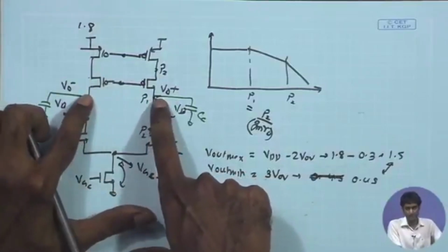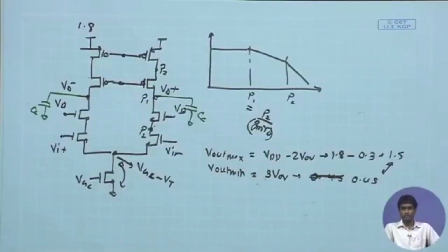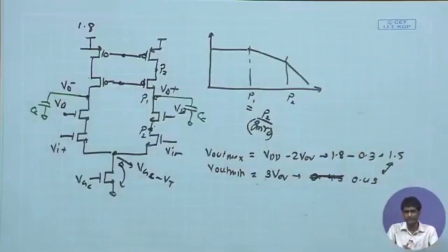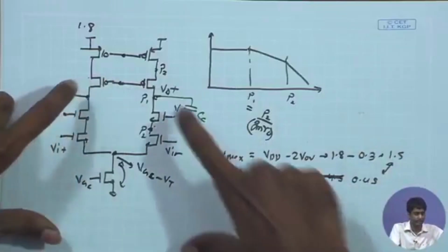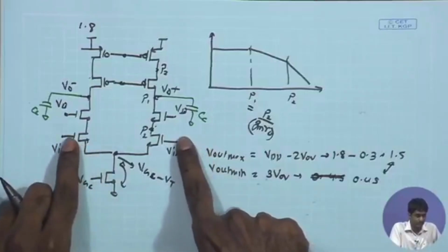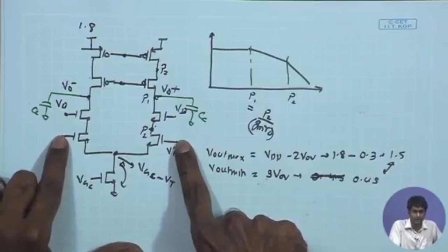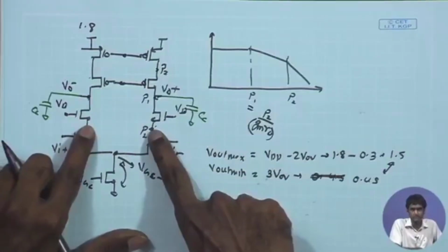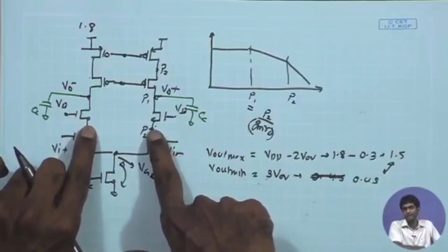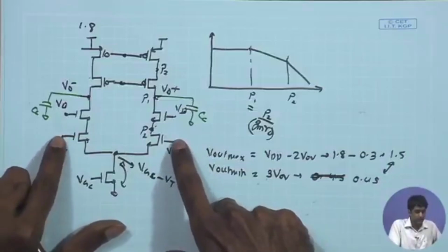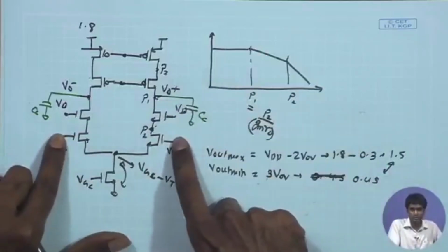So I would like this to be 1 volt, and then if I try to apply that same 1 volt over here, using our earlier scheme with resistive feedback, is this going to be a good bias point for this one? If we apply 1 volt over here, this potential we were trying to keep at the minimum allowed DC level so that I can have the maximum possible swing. So what was the minimum allowed DC potential that I arrived at?